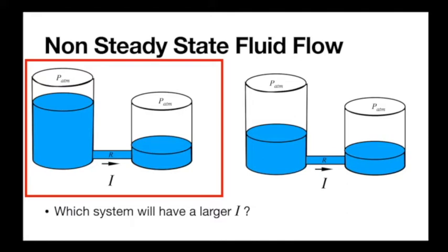And as the delta H, the difference in height, decreases, the current goes down as well. So we start with some initial current, they come closer and closer to equilibrium, and as they do, the current decreases until it reaches 0. And that can all be explained by the equation we found before. The delta P term goes away because they're always both at PATM. So the pressure is the same, but we just have this delta H being proportional to I, or negative I I guess.